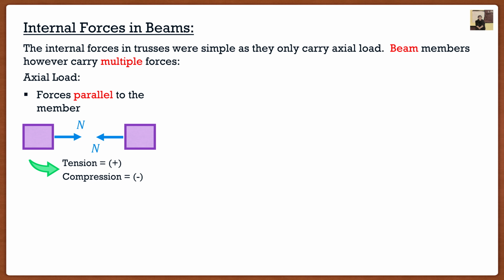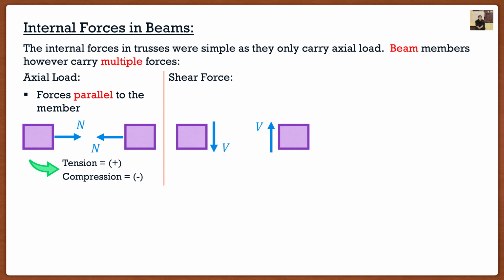Now, the one that you guys may have heard of, but we actually haven't discovered yet, is something called a shear force. All right, a shear force. And in design, this is the critical one. This is the force that kills people. And I sound dramatic saying that, but it's actually true. This right here is the killer. So if we were to look at shear force, this is going to be a force that is perpendicular to our member. So if this was my member and I were to cut it, my shear force is actually the vertical force.